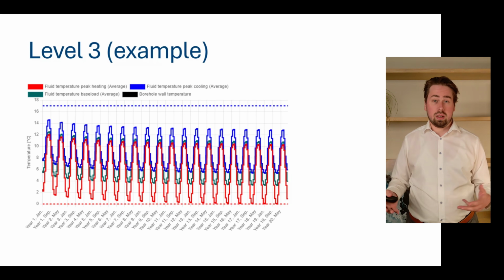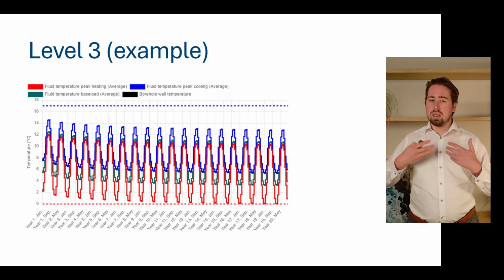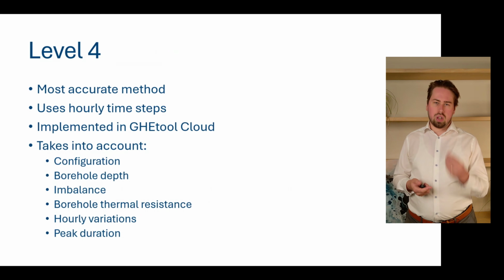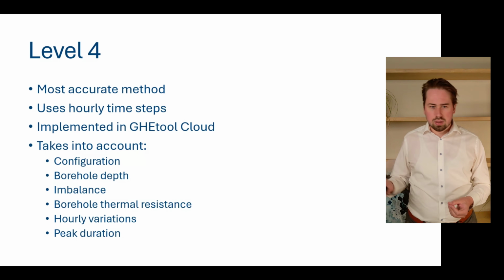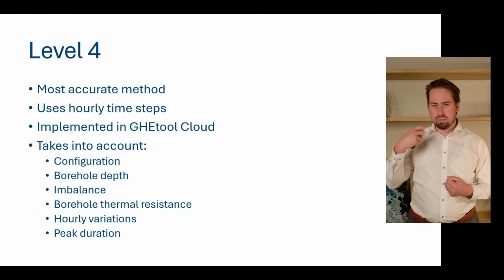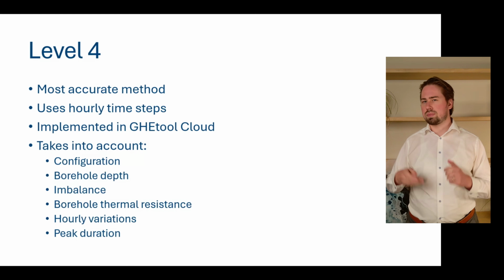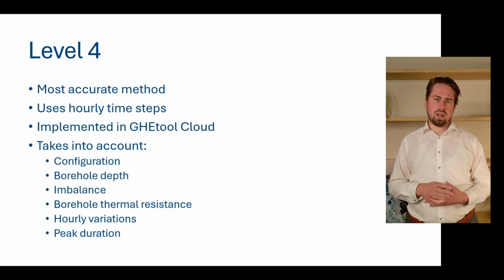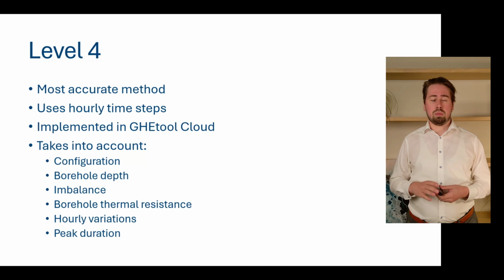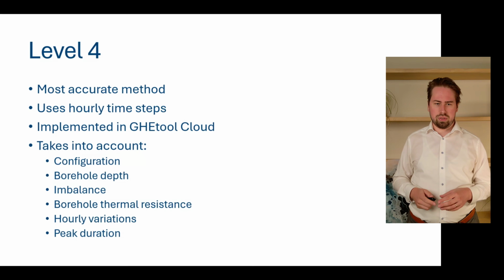It's basically the way we have been designing bore fields throughout this course, and we will do in the chapters and parts to come. And the last level, which is the most accurate one, uses hourly time steps. So we do not need an assumption for the peak duration anymore because it's embedded in the profile. We know at every hour what the borehole wall temperature is, what the fluid temperature is, what the borehole resistance is. So it's a really accurate way of designing, also when we will be looking at, for example, things like simultaneity in the next part.